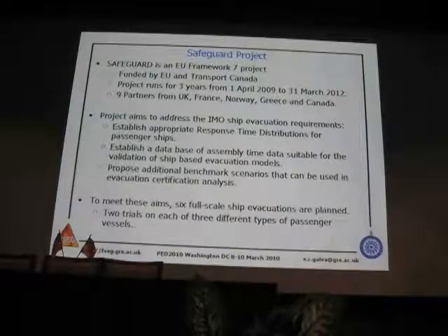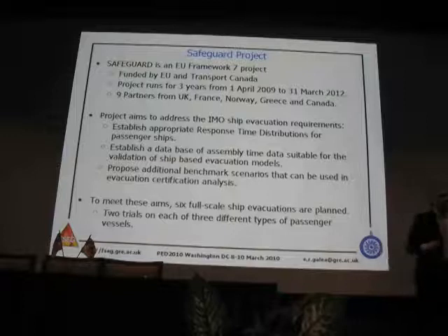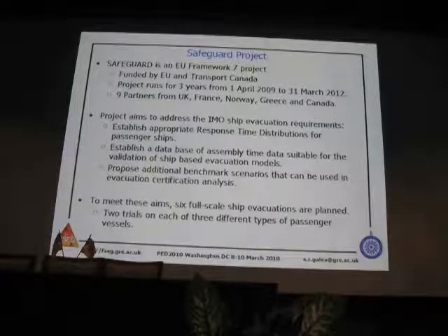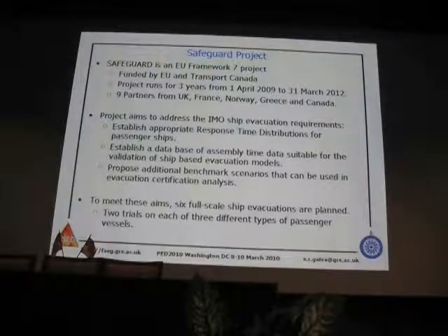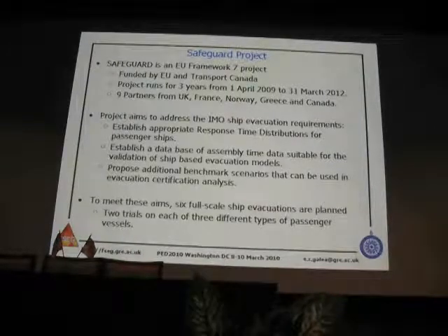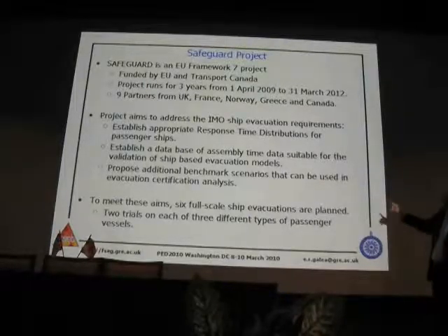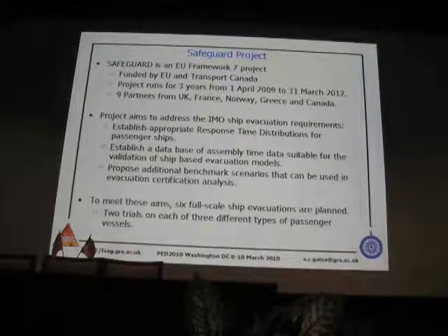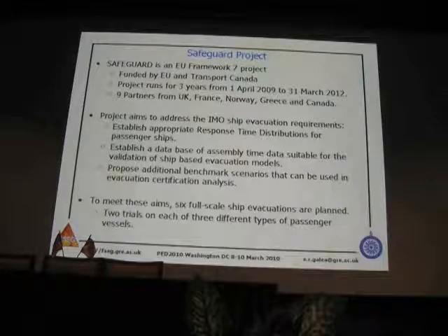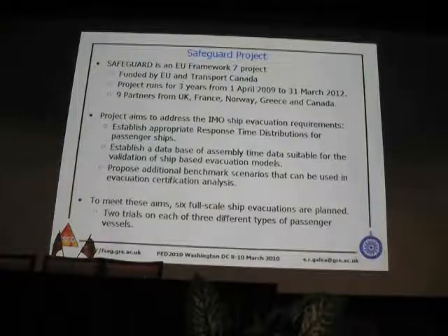And the third thing it wants to do is to establish an improved set of benchmark scenarios that are used to assess ship design for evacuation. Currently we have a set of 4 scenarios, 2 so-called day scenarios and 2 so-called night scenarios. What we're going to be doing in this project is extending that to include situations where you have a fire on board the ship and when the ship has an adverse angle of heel. So these are going to be new scenarios we're adding.